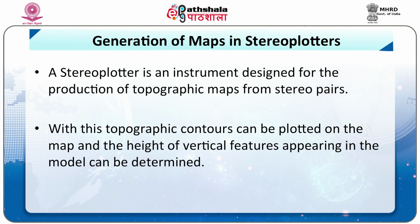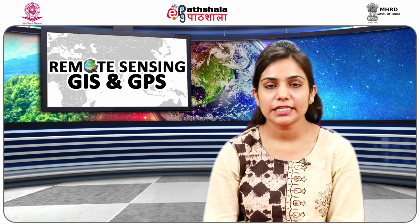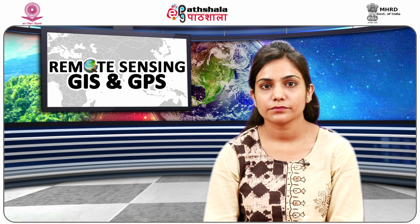It is measured by the use of a set of measuring marks, which are also called locating marks. Next information we can derive is the generation of maps in stereoplotters. A stereoplotter is an instrument designed for the production of topographic maps from stereo pairs. Two pictures of a particular area are simultaneously taken but from slightly different angles. The overlapping area of the two resulting photos is called a stereo pair.